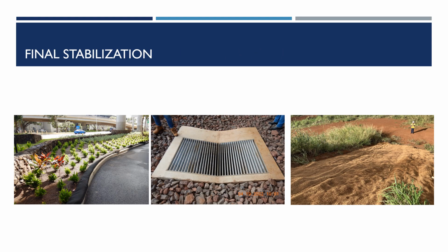Final stabilization. All disturbed slopes must be adequately stabilized, such as with vegetation. Site conditions should be taken into consideration for final stabilization measures. If site conditions are infeasible for vegetation, other final stabilization measures should be considered, such as riprap or turf reinforcement mats. Consider design approaches for PBMPs that contain sloped areas such as vegetated swales. Components for velocity dissipation or flow control, such as check dams or level spreaders, may be included depending on site conditions.